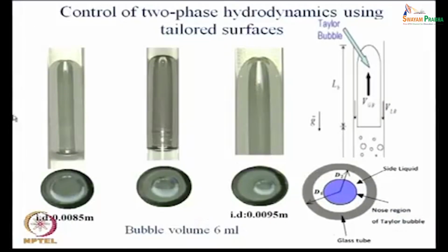We found out that the bubble does not rise beyond the critical diameter. More or less we found the diameter to be 4 millimeters, and past studies have also reported an identical diameter. Okay. So, we found out that more or less in this particular case the bubble rises only after the tube exceeds a minimum critical diameter. But once it begins to rise, it just takes up the same shape that we had observed for a bubble in larger tubes.